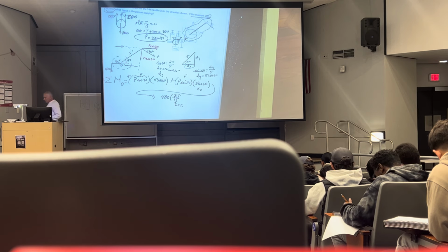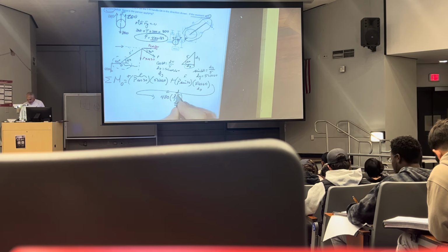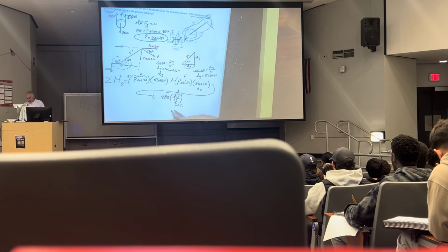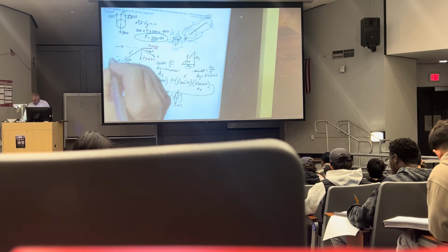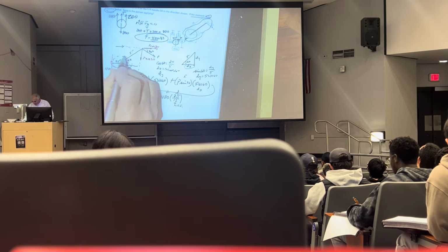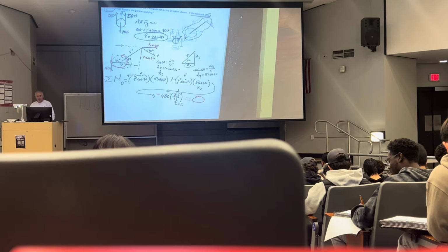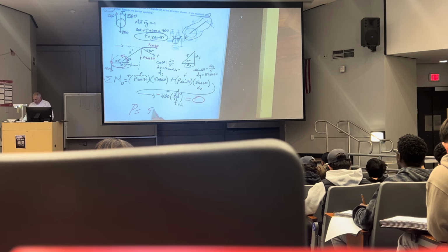So I got to convert. And I did. There's the force, there's the distance. Positive or negative? Well, if I move this along its line of action and go around O, what is that? Counterclockwise. Damn it, that's negative, and that must equal 0. So you can solve for P. P is equal to 50 at an angle of 60 degrees.